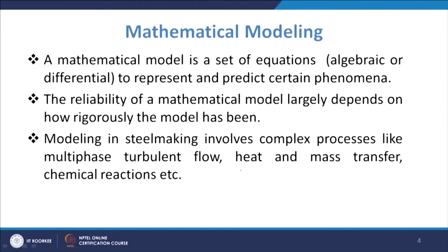If we talk about the mathematical modeling, as we know, a mathematical model is a set of equations, algebraic or differential, to represent and predict certain phenomena. So, that is how the mathematical models are made, and these equations are governed by certain principles. Just like if you go for the flow in the tundish, since the molten steel is a fluid and it is flowing inside, you will have certain conservation equations. So, you will have the continuity equation, or you may have the momentum conservation equation or so.